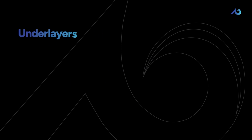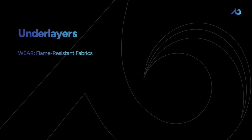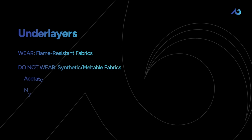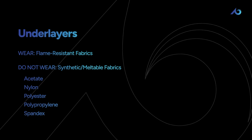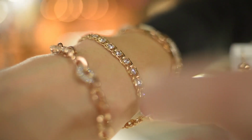Now, what you wear underneath all that gear also matters, in case there's a tear or breach in your outer layer. That means you should wear flame-resistant fabrics underneath your arc-rated gear. But most importantly, never wear synthetic, meltable fabrics like acetate, nylon, polyester, polypropylene, spandex, or anything that can melt into your skin and cause serious injury or complications. Of course, the same restriction goes for things like zippers, jewelry, or other accessories that can melt.